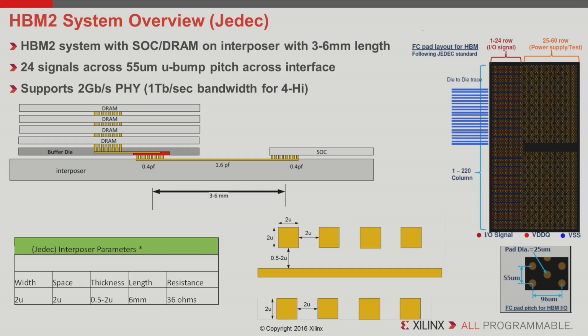So the point to watch out for is that this particular scheme may not be readily usable. If you go with a 90 nanometer 4X technology from a foundry house, and you want to stay with the standard offering, you might not quite get a 2 micron thick metal wire, maybe more 1.2, 1.4. So the design templates have to be understood and tweaked accordingly.